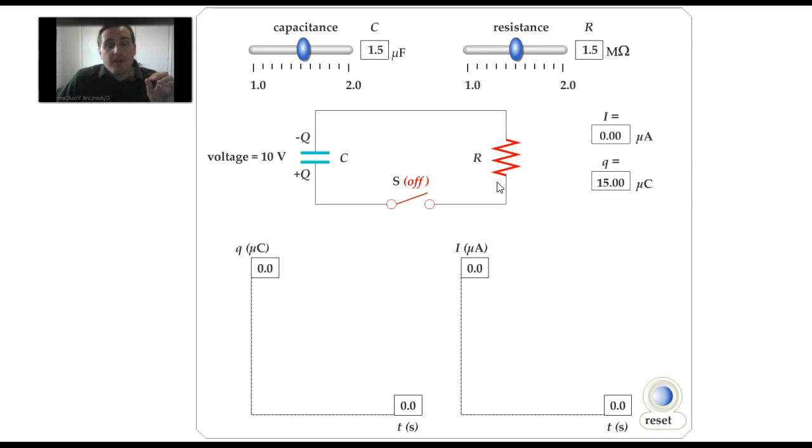In fact, one very useful application of an RC circuit would be a flash circuit. A flash circuit is like, say, when a light bulb discharges, say when you're taking a flash photograph. When a capacitor discharges through that resistor, typically we want it to happen very quickly, so the resistance is very small, so that the time constant is very small. But that's what we expect to have happen in a flash circuit.